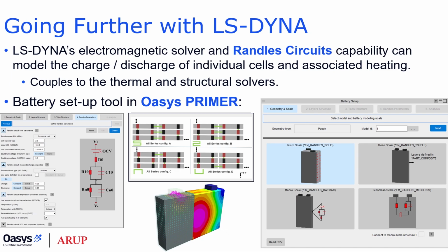The Randles circuit capability in LS-DYNA allows us to model the electrochemical response of the individual cells in varying levels of detail. The ability to accurately model the charge and discharge cycles and the associated resistive heating allows us to study the consequence of abusive electrical loading. In Oasys Primer, there are dedicated tools to help the user set up Randles circuit definitions, including the different scales, for example, solid, BatMac, T-shell or meshless. It also has an intuitive interface for Randles circuit parameter definition and tools to define arrays of cells, including options for busbar interconnection.